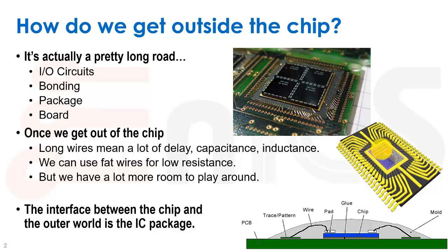Okay, so we can look at this. This would be our chip. Our chip has some sort of a pad or an I/O connected to a pad, and the pad is connected to a wire like that. These are the bonds. They're connected to the package. This is already part of the package. This will go down onto the board, and we'll solder that onto the board, and then it can be routed to another chip.